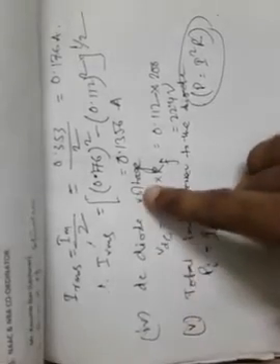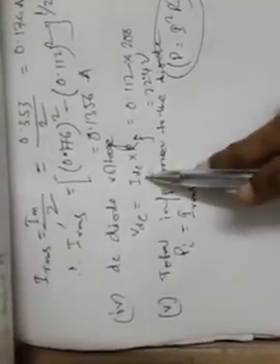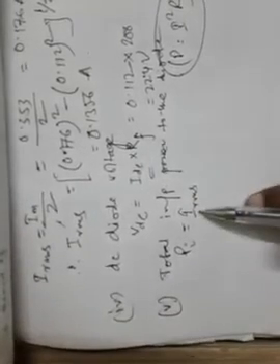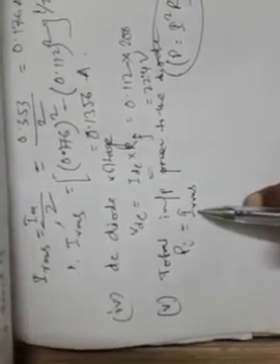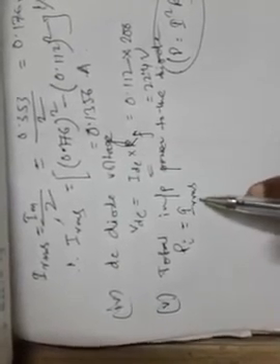Since this is DC diode voltage, it is indicating the output of the diode, and the output of the diode is primarily having DC components, but at the input of the diode it is primarily having the fluctuating components, that is the AC components, and AC component means you need to consider the RMS values. So for output calculation we have to consider IDC, and for the input calculation we have to consider the IRMS.